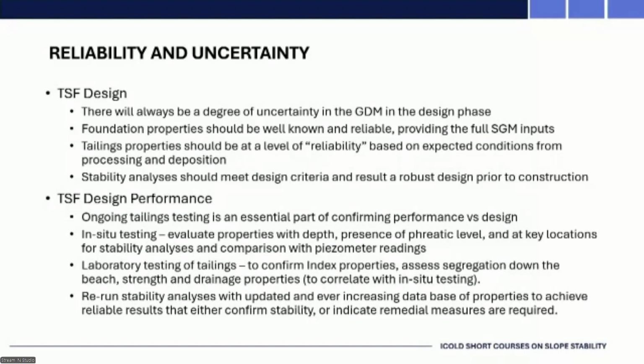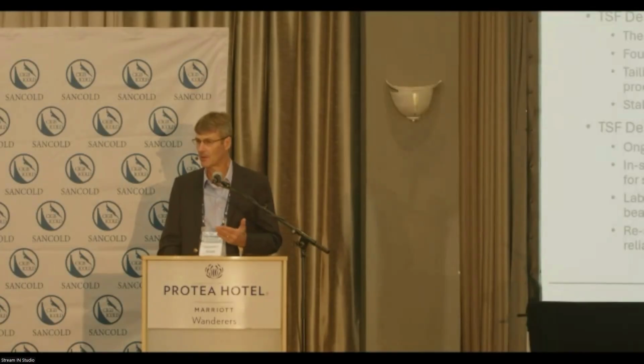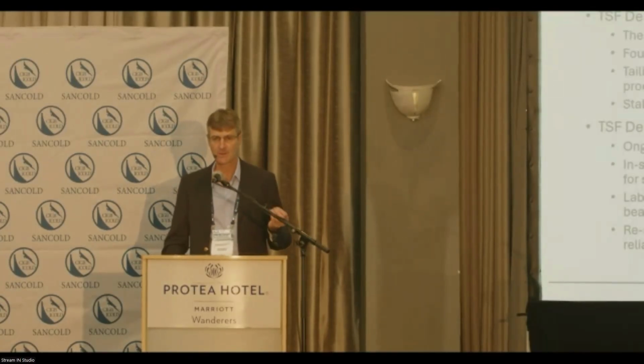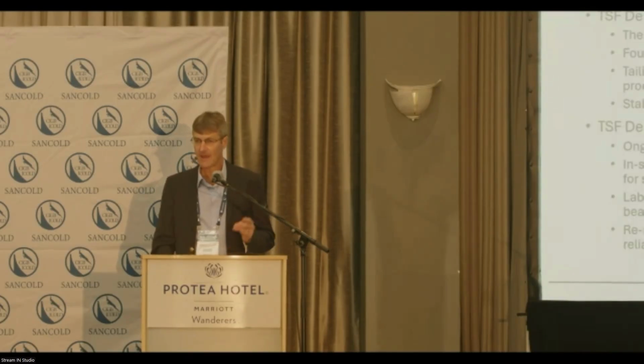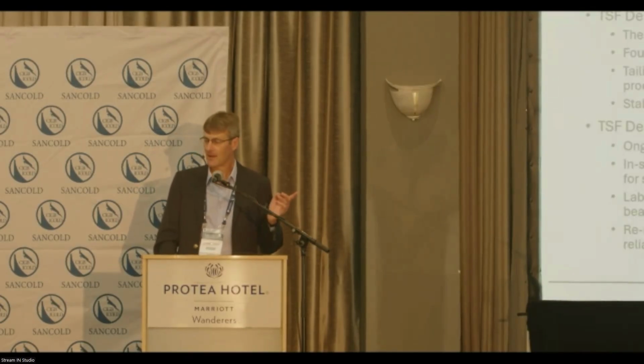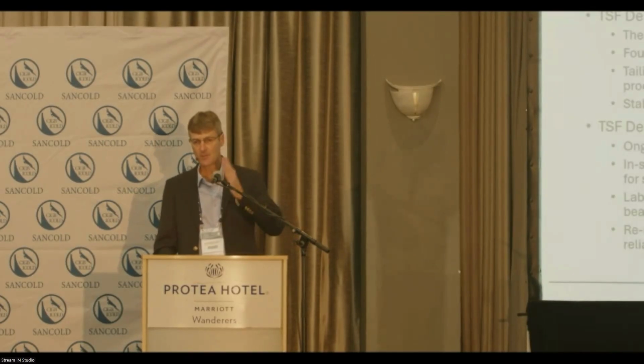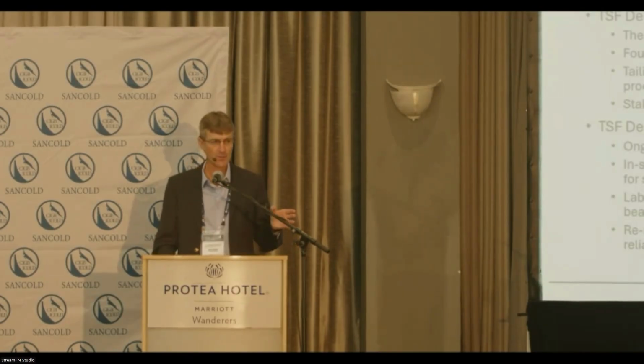In situ testing is a very, very, very valuable tool for us to go in and every 2 to 3 years keep doing further testing. So it's not just index testing, but it should be shear strength and other forms of testing that help us. And we should be correlating the probing tests with lab tests. So relying just on probing tests is probably not enough.